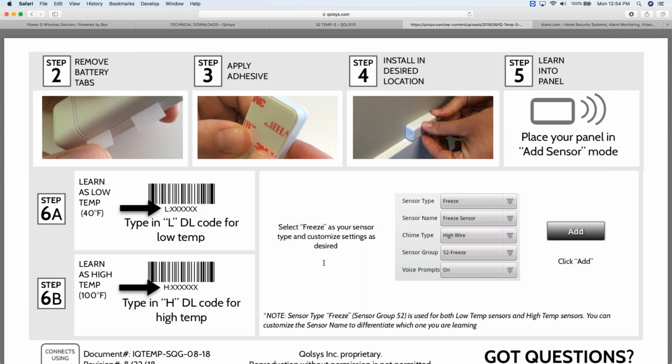But yeah, totally. We got this hardwire translator, we went and ordered 10 hardwire smoke detectors, wired them up in our office, and it works beautifully. So, good question: how many 2-wire smokes can be hardwired into our translator? The answer is up to 10. The only thing to keep in mind is you want to make sure that you're using our hardwire 16F.